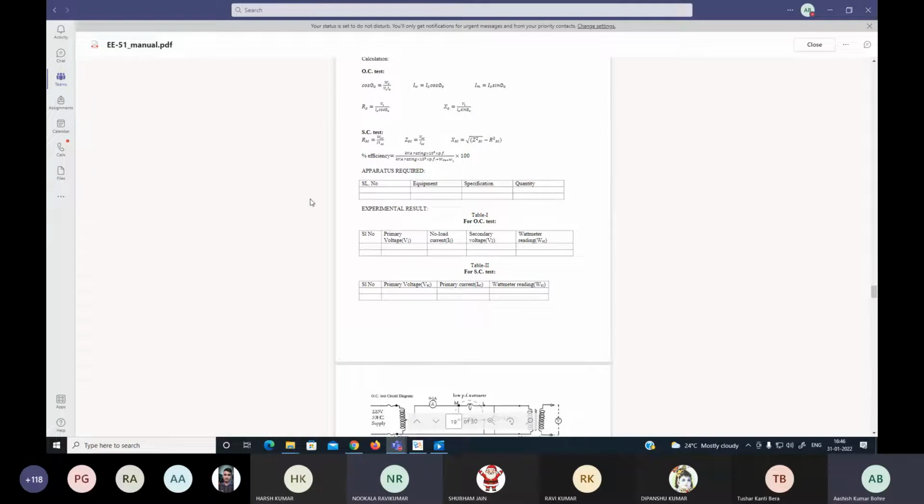After that, as I told you, V1 equal to 55, one reading is sufficient here because it is performed at rated voltage. And V2 equal to 230. Here this is not WSC, this we have to correct, or you correct it. I have already corrected it in the video. This is W0 for the open circuit test. This will give you the open circuit losses, the iron losses, which are fixed losses. So you will get W0 for the open circuit test.